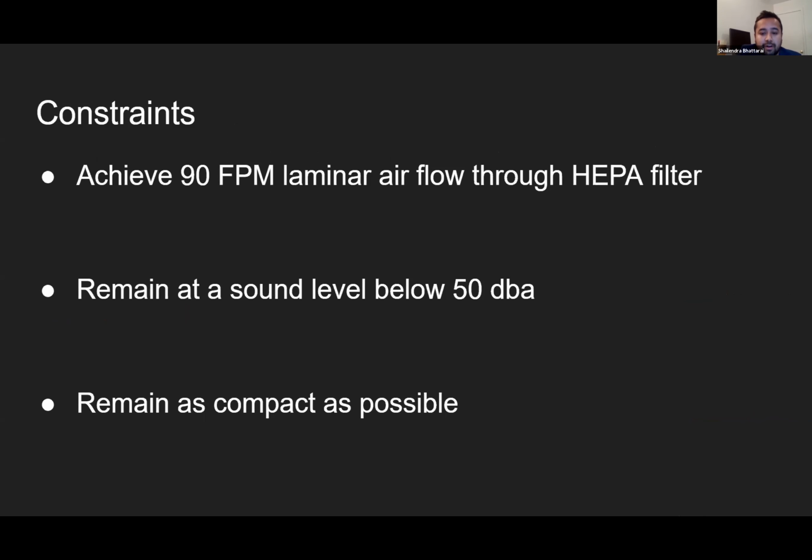The final design of our project has to match certain design constraints. At first, it has to achieve a laminar velocity of 90 feet per minute passing through the HEPA filter. Secondly, the overall system has to produce a sound level below 50 decibels. And finally, the overall system has to be as compact as possible.